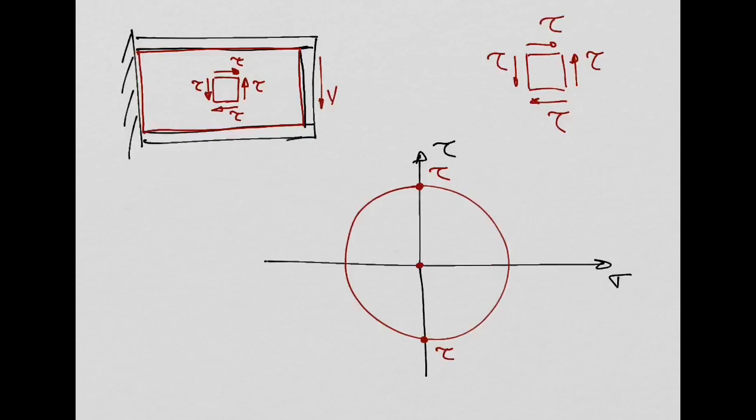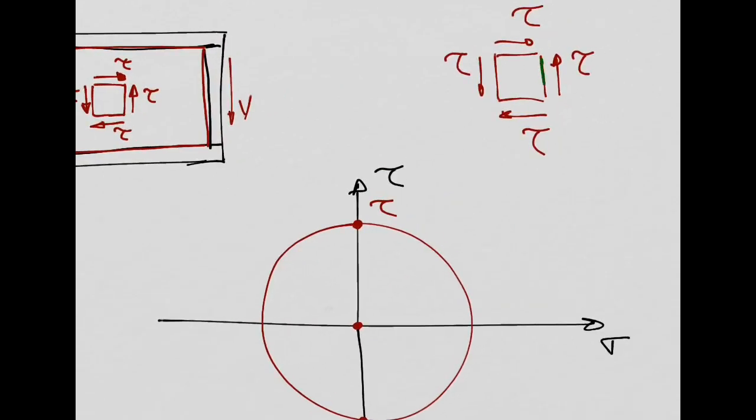So now look at this. If you take this shear plane here, this one in green, the stress component you have in this shear plane is this tau stress only. You have a zero direct stress, right? A zero sigma stress. So that's why you have this point here. Look, this point in the circle has only a tau component, right? Sigma component is 0, right?